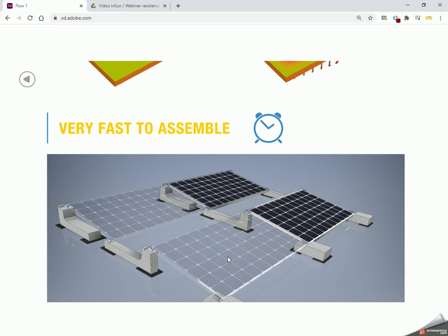It is a protective sheath, an EPDM sheath. After that, you just have to put the ballast on the sheath. Each ballast is equipped with an M8 bushing, so you do not have to make holes in the ballast. At the end, you install the PV panel using a kit of central or terminal clamps that we already provide with our kit.